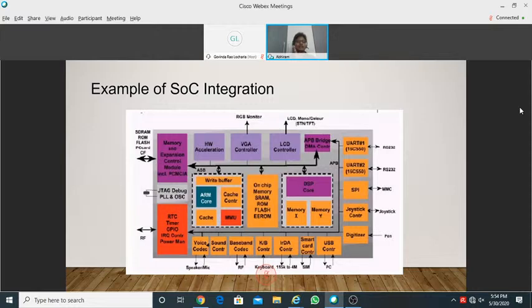Going to the next slide, I am showing a particular example of how an integrated SOC looks. You can see DSP cores, ARM cores, on-chip memories, and memory slots for the DDR and so on. So a typical SOC after it has been integrated with all the soft and hard IPs will look like this. As you can see, it's a very huge, complex chip. Just by integration of these IPs, we can't achieve anything, because that's where our focus on verification comes into the picture.